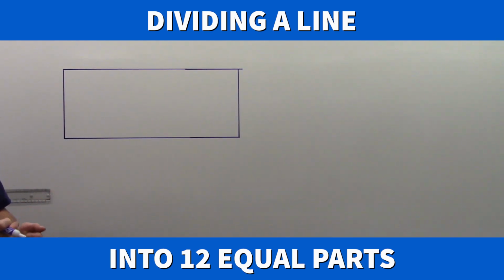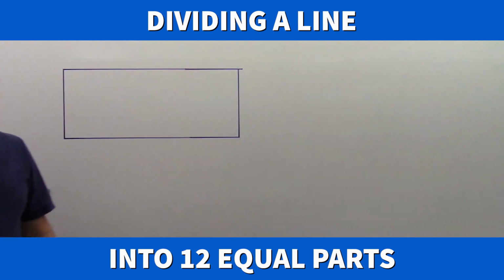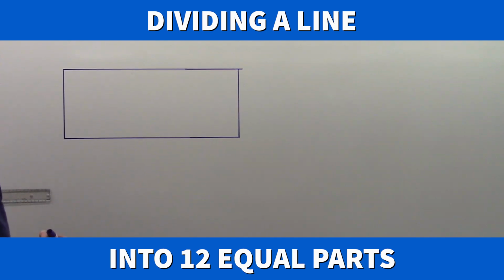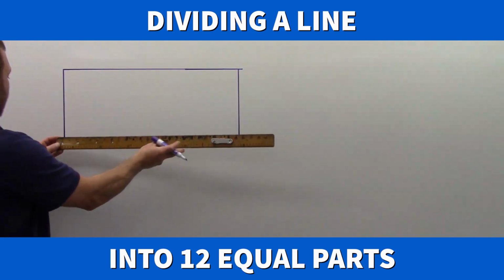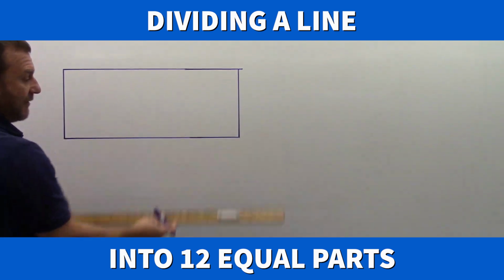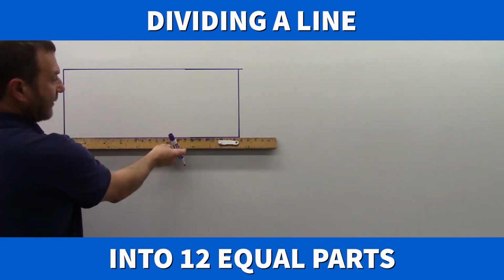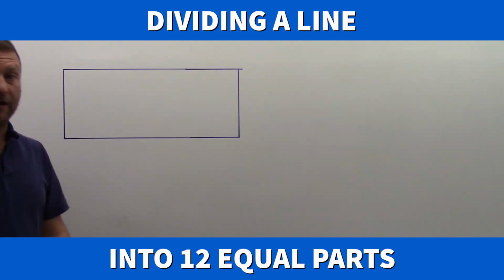And if we get into something really small and we want to divide this into 12 equal parts, and maybe it's something like 2 3/32 of an inch, to replicate that 12 times by measuring is a really inaccurate way of dividing that. So what we can do is use a technique called your ruler on a diagonal. Now, what we do here is I have my length, but it's not easily divisible by 12. I actually have about 24 and a half. So I don't even want to bother trying to calculate that out.